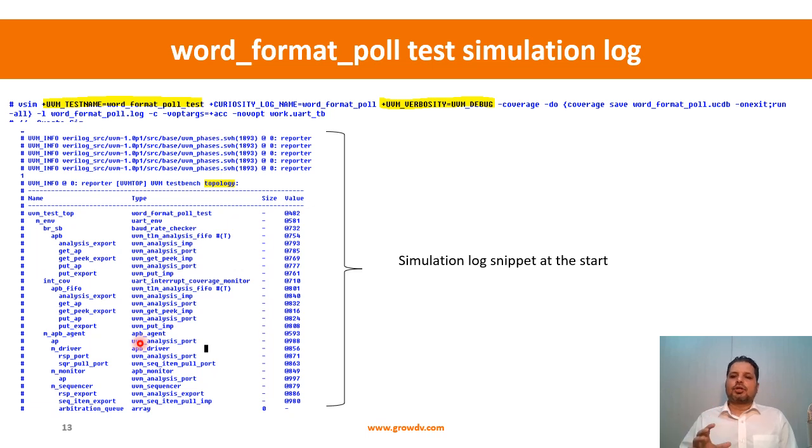You will come to know the configuration, right, and what configuration we are running. You remember we had structural configuration and functional configuration. So this is like the structural configuration of your test bench. For the functional configuration, eventually each of the config objects will be printed. So using those two, you will come to know how the test bench has been configured. So the first step in the log is to find out the configuration in which we are running the test.